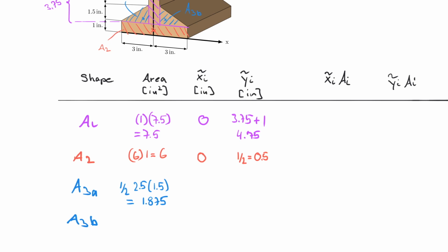So for my x direction first, I have to take the 1/2 inch, so 0.5, because that's half the width of the middle piece of A1, plus, so sorry, in this case it's actually negative, right? We're talking about the piece here on the left side, so I'm going from here to here, so that's negative. So minus 0.5, and I just put it in brackets, plus the 1/3 times 2.5. That is my distance here. And that distance happens to be negative 1.33.